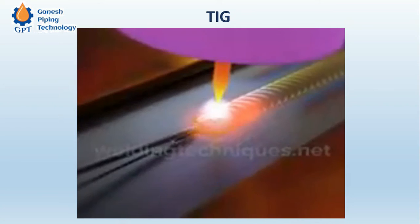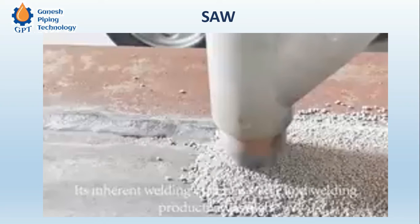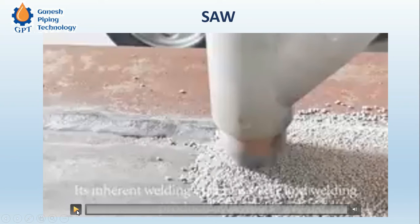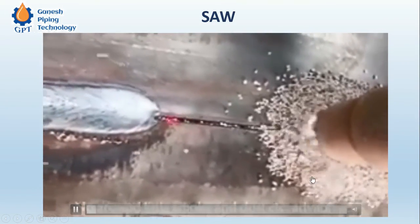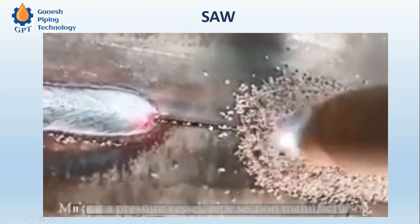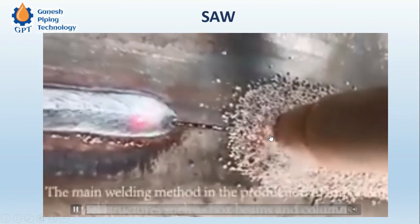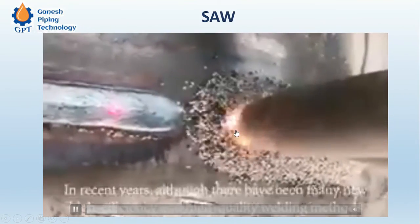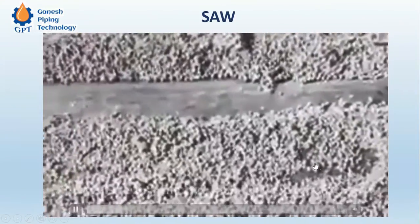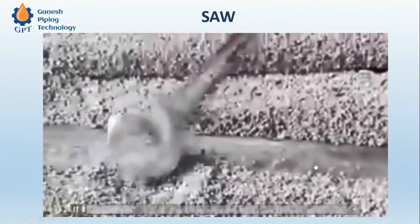Now moving forward, this is submerged arc welding. This is basically a tank or a big size pipe, which is placed on a special machine called a positioner. Now let's see here. This is a joint we can see, and the arc is struck beneath the layer of flux. So we cannot see the arc, and this flux layer is protecting the molten metal from getting oxidized.